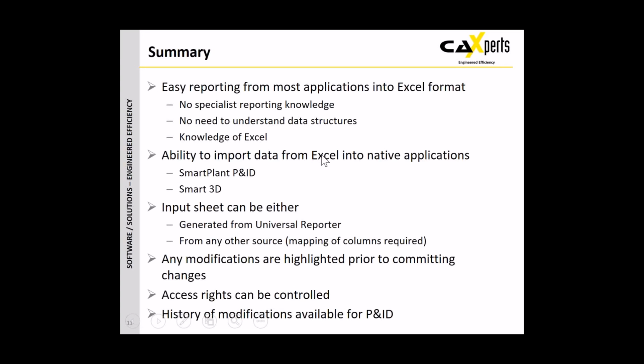And then finally, on the P&ID side, there's this history of modifications available that Christine brought up in the dialogue, showing you all the attributes that were changed through Universal Reporter, what the changes were, and when they were done, and who did them.